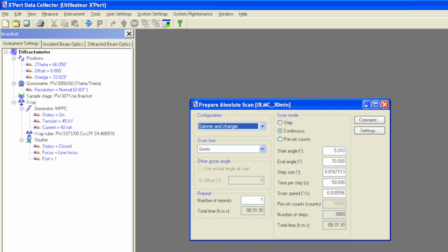The scan speed can vary from lab to lab, depending on the power of the XRD. Typically, a 30-minute scan within the range of 7 to 70 degrees is good enough to perform the Rietveld analysis. While for fresh pastes, the scan should be acquired within 15 minutes to prevent the drying and the carbonation of the fresh samples. For some specific cases, such as the comparison of polymorphs of tricalcium silicate, enhanced angular resolution and peak intensity for a selected range of the pattern can be more useful than the full pattern.